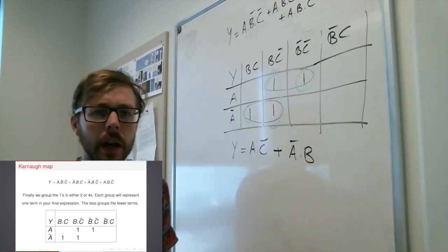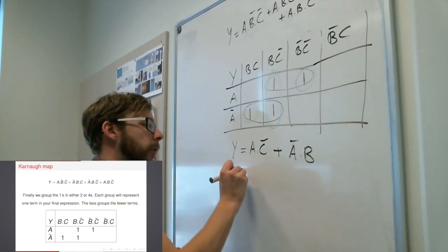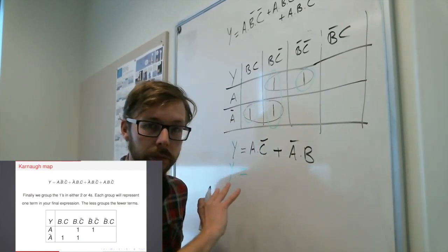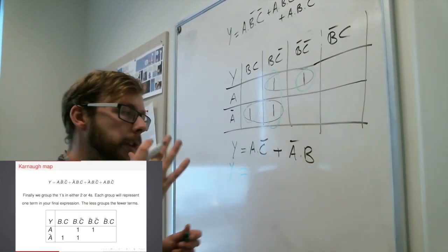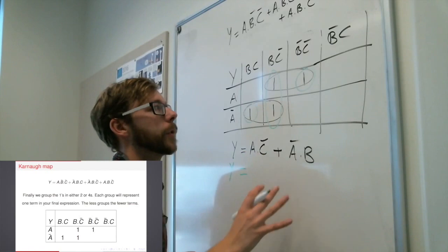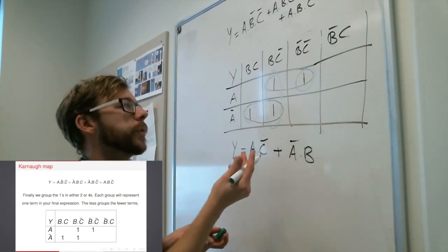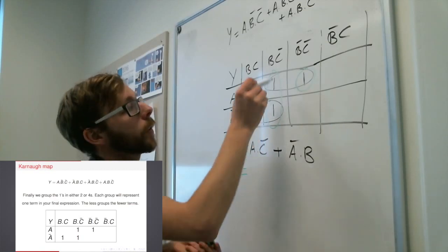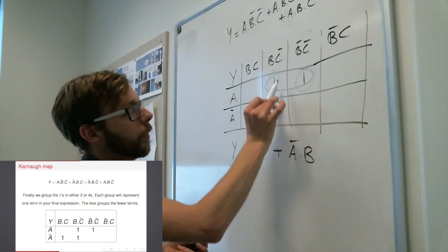But just to give you an example, let me show you how to do the green one as well. It's exactly the same. And remember, while the output will be written differently, logically, it's exactly the same. So depending on your different inputs, it will give the same logical output as this. Once again, I usually start with my biggest group when I'm doing Karnaugh map groupings, and my biggest group is this vertical group here.